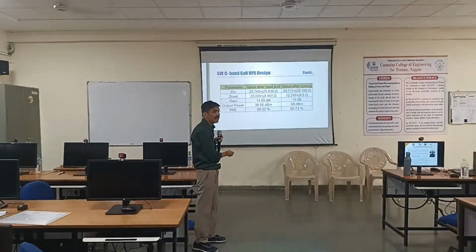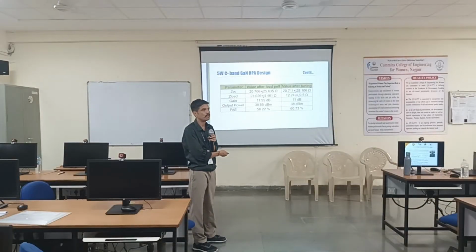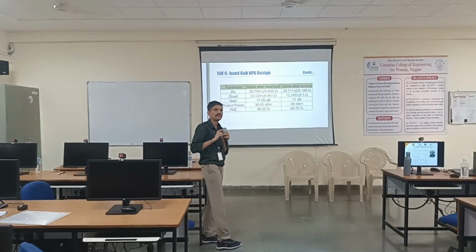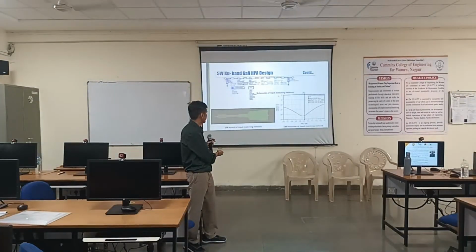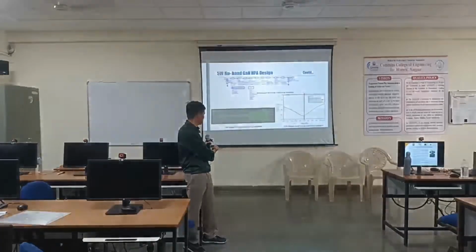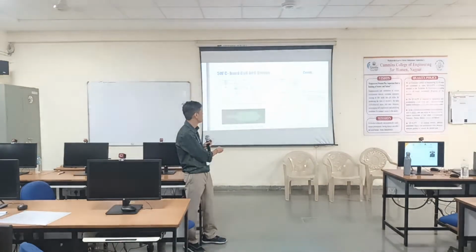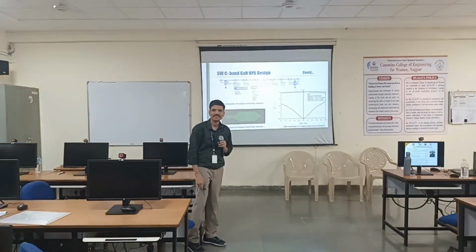You could see I could get 60% efficiency at low frequency. But when you go to the higher frequency, even 1 mm or less than 1 mm, you change your width or length, whole PA performance will move up. So see the beautiful response. Everywhere gain is flat. S11 is below -10 everywhere. So this is input matching. Similarly, output matching also very clean. Throughout the 2 gigahertz, I could get the S22 less than -10 dB. Gain is dropping less than 1 dB only throughout 2 gigahertz of a band, 3 to 5.